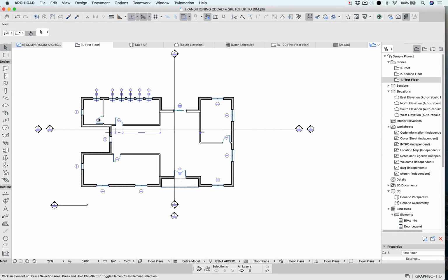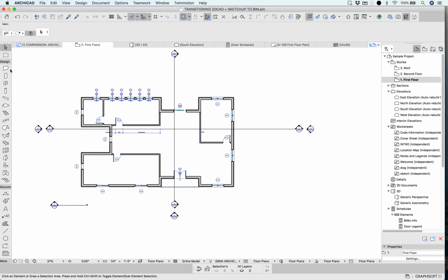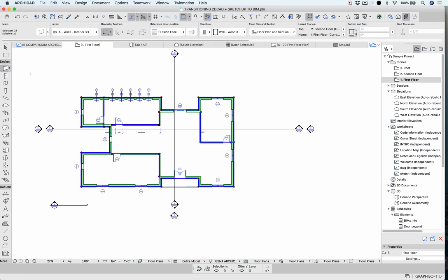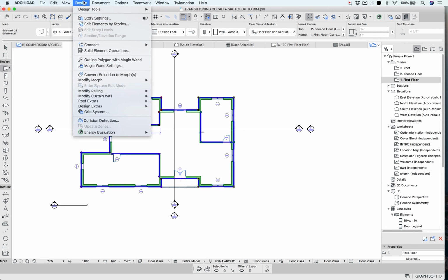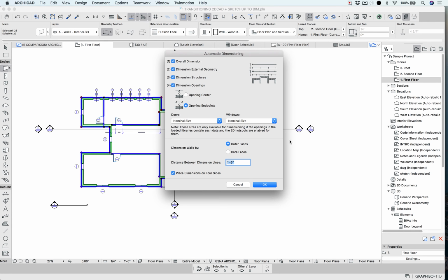I also just want to show you our quote unquote easy button, right? So I can also select this entire structure. And what we'll do, I want to select just my walls here. So I can select Command A or Control A, select all of my walls, and then I can say, hey, please give me all of the dimensions that you can.